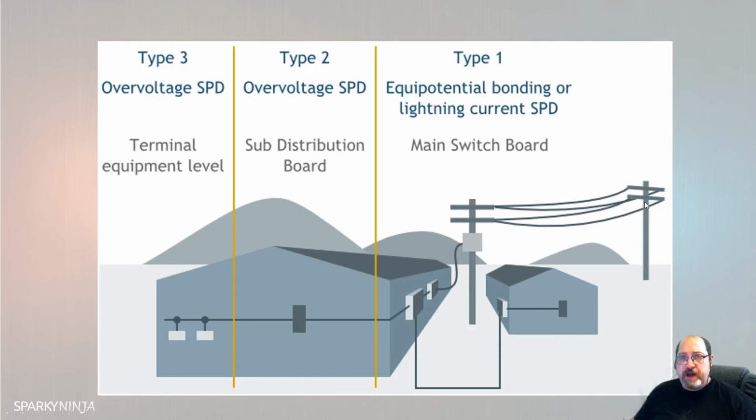And whilst there'll be an Earth at the transmission end for obviously the network, here your Earth is locally sourced. So when lightning and voltage hit this, they're going to be going down to that Earth. Once this voltage has gone underground into the mass of Earth, it starts to lose energy, it starts to disperse, but it's seeking a better Earth, because ground is not brilliant. It's not a brilliant conductor for the voltage.